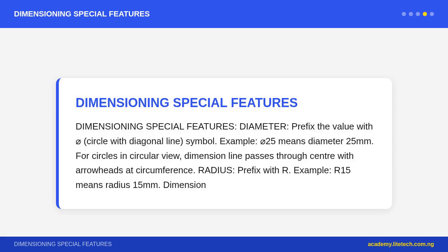Limits and tolerances. Tolerance equals permitted variation. Example, 50 plus or minus 0.5 means the dimension can be 49.5 mm to 50.5 mm. Upper limit, 50.5 mm, lower limit, 49.5 mm. In mass production at Nigerian factories, tolerance is critical. A 1 mm error in a car part may cause failure.